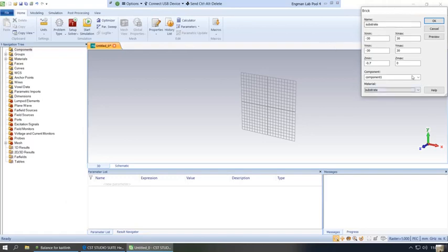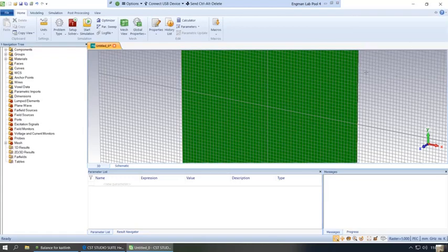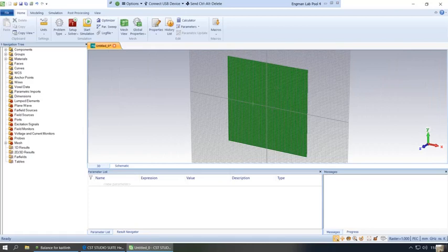We have all of our values defined. And you can, just as a sanity check, hit preview, and that will give you a preview of what it's looking like. Notice that it expanded the size of the working plane, so right now we're too far zoomed in. The way that we can get around that is either scrolling out on the scroll wheel of our mouse, or if you don't have a mouse, you can hit the space bar. Select in your area, select in there first, and then hit the space bar.